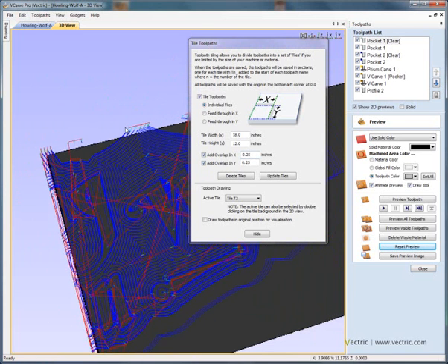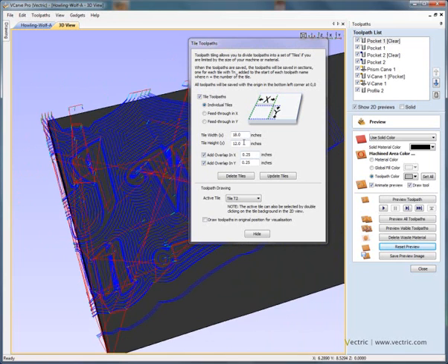This allows us to machine past the 18 by 12 boundary, and then once we've finished machining that panel, we can run a simple 2D toolpath around the 18 by 12 area, cutting around the outside to give us a very sharp, precise edge, so that the mating faces will all match up and the panels will fit together to give us our finished sign.